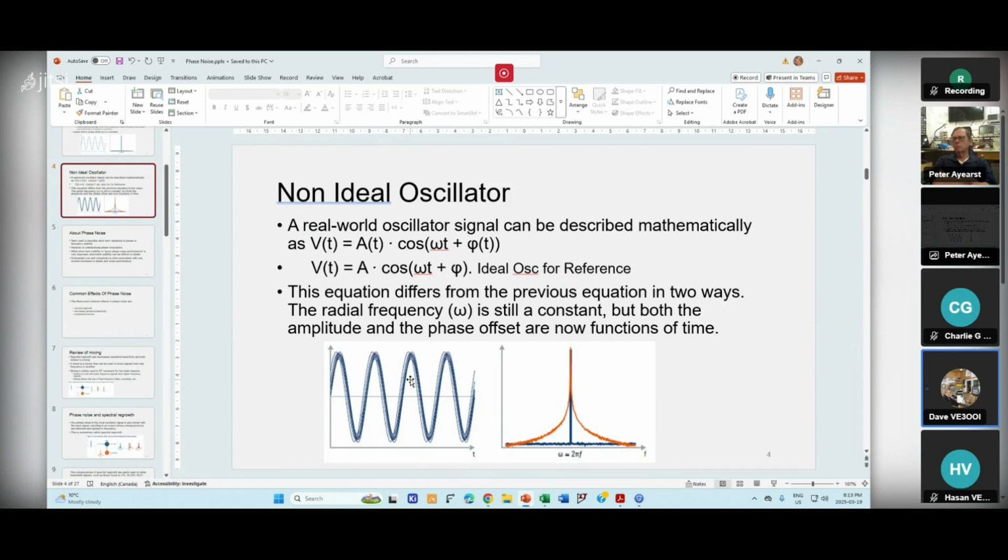What that means is when it quantizes, you get a number, and that last bit might go up and down, so you might be off by 1, or maybe it might be worse, and the last 2 bits might be off, and that's going to add a lot more error, right? So Peter's right. It has to do with how it's being measured. Does that make sense? All right, that makes sense.